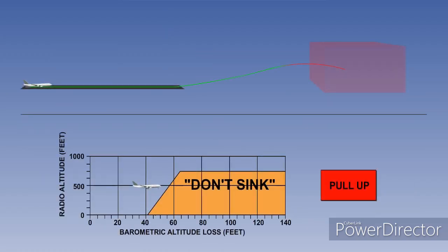Mode 3 provides an alert if a descent is made during the initial climb or go-around. Mode 3 is effective between 50 and 700 feet radio altitude and generates the alert when the aeroplane has descended by 10% of the existing radio altitude. It is not armed during the approach until below 200 feet radio altitude. The oral alert is repeated every second and a half until the flight condition is corrected. "Don't sink! Don't sink!"